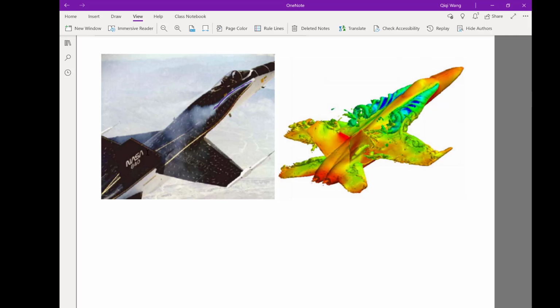And now this is a computational fluid dynamics simulation. And the vortex, which is indicated by this blue region inside, actually breaks down, like in this region. And the chaotic flow after the vortex breakdown goes exactly over the vertical tail. So a chaotic phenomenon like this has a lot of different frequencies. And as long as one of these frequencies resonates with the vertical tail, the airplane is going to vibrate a lot. So this is an example of a numerical solution of partial differential equations.